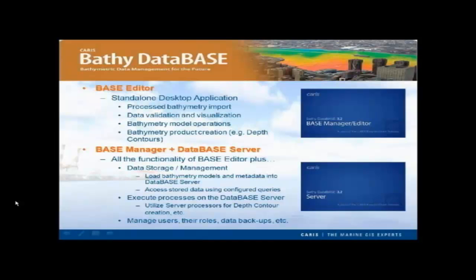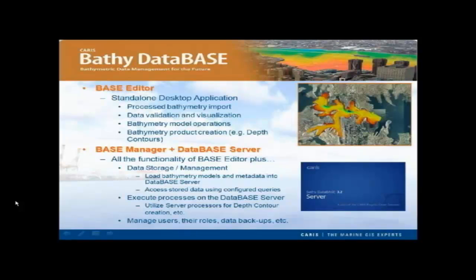So getting back to the Bathy DataBASE product suite, it's definitely quite scalable to meet the requirements of each individual user. So to start with, we have Base Editor, which is a standalone desktop application. Base Editor is great for small to medium users who need some extra tools in bathymetric compilation and data management. It's great for bringing in data from various different sources like multibeam, single beam, LiDAR or historic data, and then combining, validating and visualizing the data. Base Editor is also really handy for bathymetric product creation such as soundings, depth contours and depth areas, all which can be used to help make ENCs and other products.